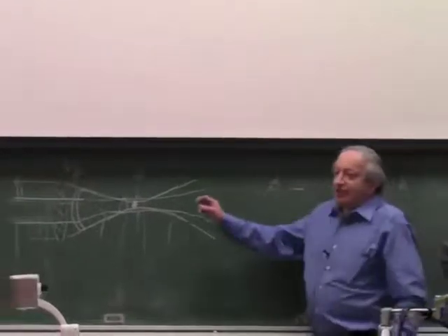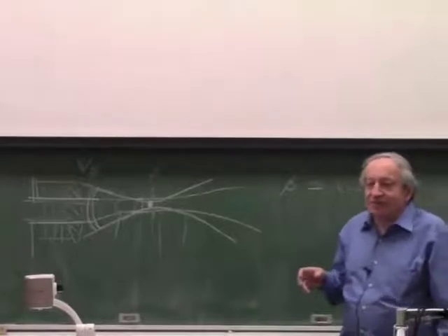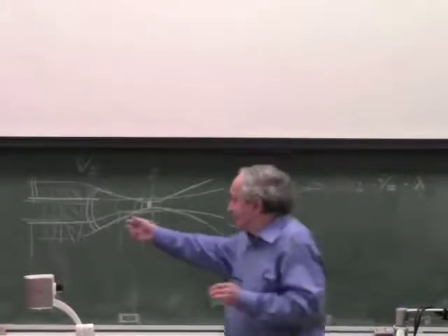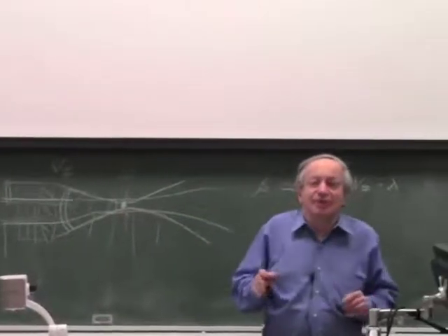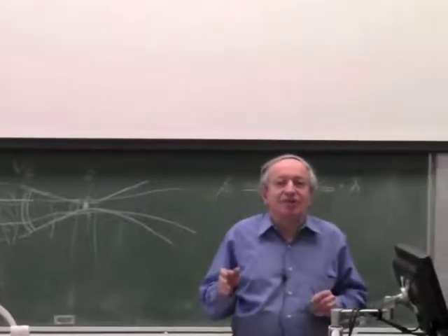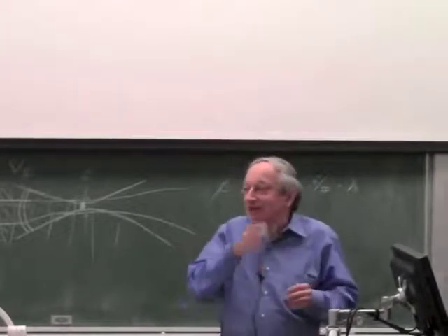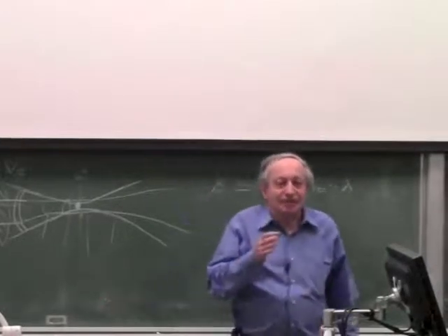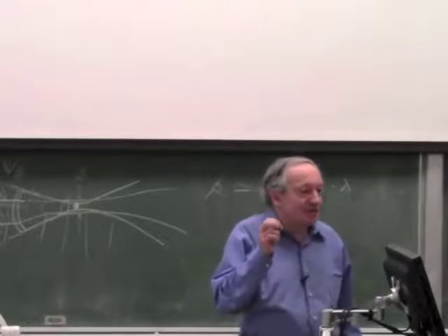Because in diffraction, if you use a shorter wavelength, you can resolve more. Simply because everything scales. The picture scales, everything gets smaller, the waves get smaller, so the spot gets smaller. And this is the reason when you want to make chips, you use UV or extreme UV instead of blue light: when you work at the diffraction limit, you have to make the wavelength shorter and shorter to resolve teenier and teenier objects.